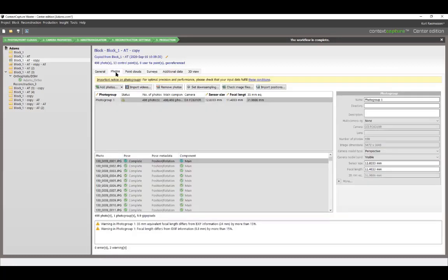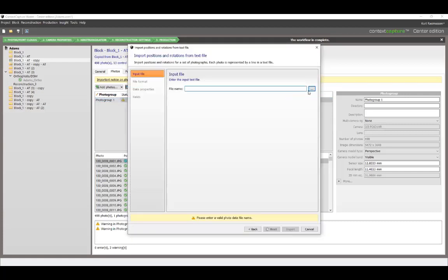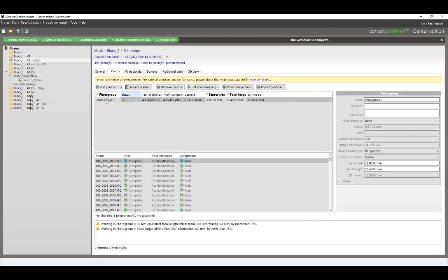Now, if you had a drone that you do PPK, where basically you're doing a process that's going to give the actual photo position accurately. So it could be going to a base station and the drone knows where it is and the photos know where they are when they're taken, but it's not locked into any coordinate system yet. So you're going through a base unit to do that stuff. At which point then for the photos, you have another data file that says photo 101 is this XYZ. You can then import the photo positions, and I don't have a file, so it won't let me go through these fields, but that's a way that you could bring in accurate photo positions right in this location here.